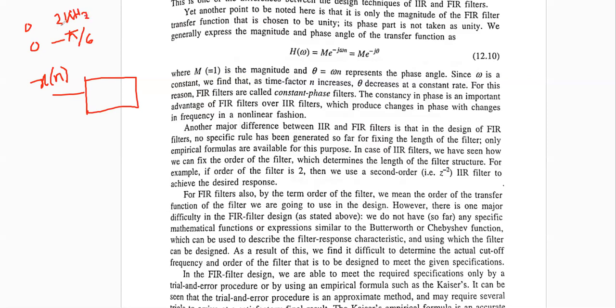Now for each and every frequency component, there might be some delay, and when it reaches the output as y[n]. So how many frequency components do you have in x[n]? You have actually 2k frequency components. You have 0 and in between. So you have a lot of frequency components inside x[n], an infinite number of frequency components.